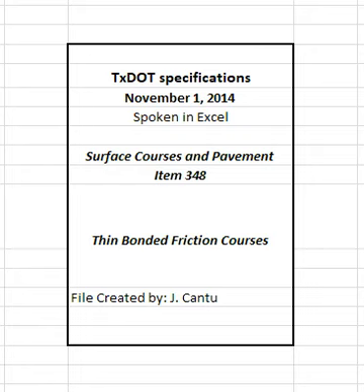4.4.2.1.15 Development of JMF2. Evaluate the trial batch test results, determine the target mixture proportions, and submit as JMF2 after the engineer grants full approval of JMF1 based on results from the trial batch. Verify that JMF2 meets the mixture requirements in Table 8.